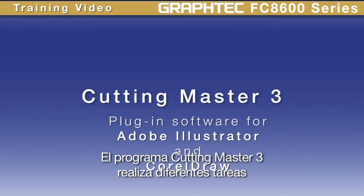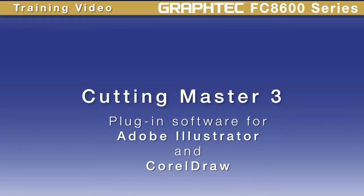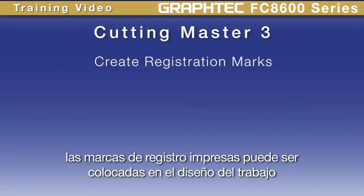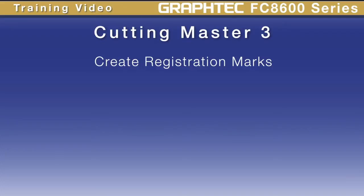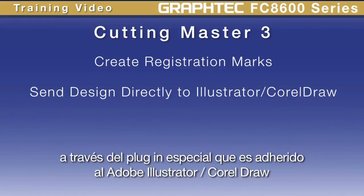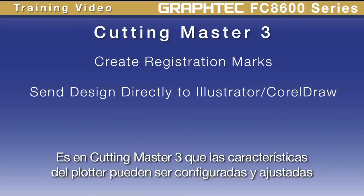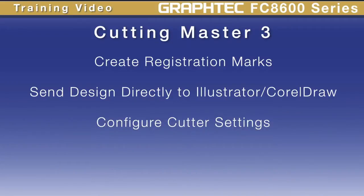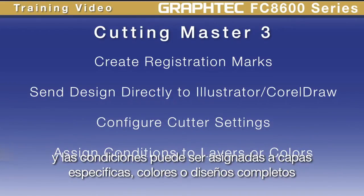The Cutting Master 3 application does several tasks. After creating a design in Adobe Illustrator or CorelDRAW, registration marks for the print and cut process can be placed on the job design. The design can be sent from Adobe Illustrator or CorelDRAW directly to the Cutting Master 3 application through the special Graphtec plugin that is added to Adobe Illustrator and CorelDRAW. It is in Cutting Master 3 that cutter settings can be configured and adjusted, and conditions can be assigned to specific layers, colors, or whole job designs.